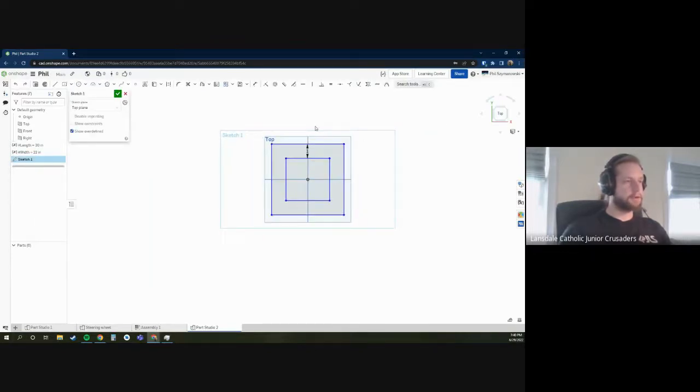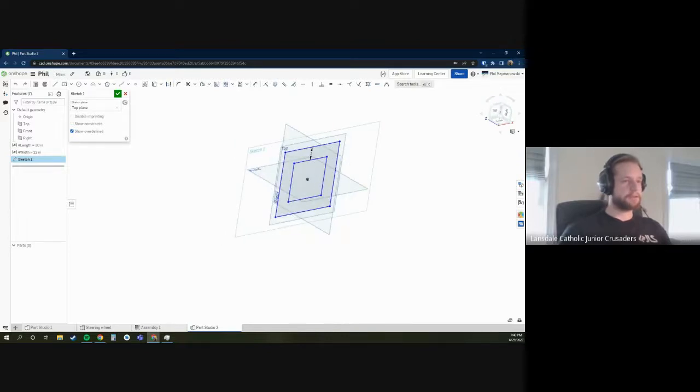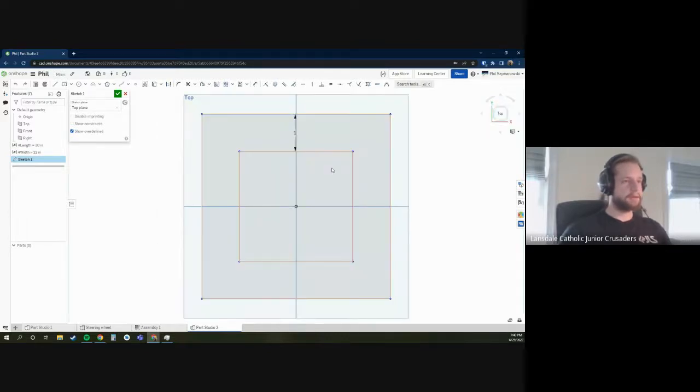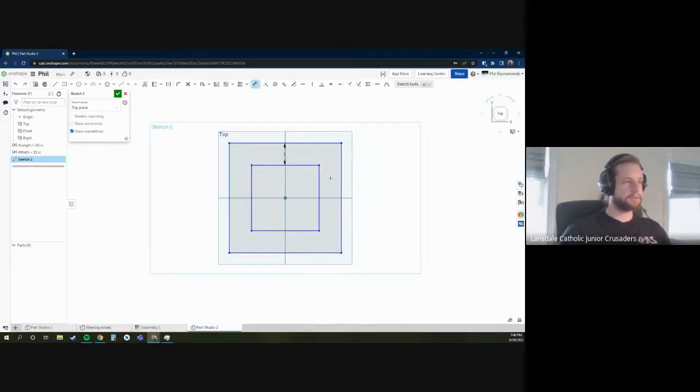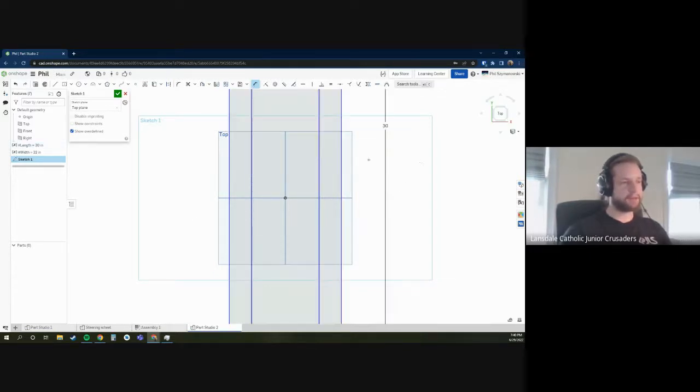So let's see, where's the front? The front is that way. So I'm going to dimension. Where's my D key? There's my D key. This is going to be #length. So does everybody see I'm utilizing that variable length, and it automatically is going to make it that value.